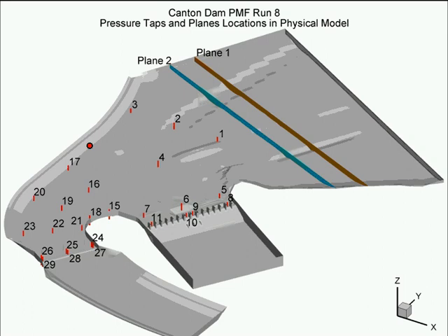What we used CFD for was to test a large number of different approach channel alignments as we come through this area here to find one that, one, gives us the water surface elevations that we desire, and two, tries to minimize excavation requirements. The two spillways are so close together that they are hydraulically linked, if you will, so a change to the fuse gate spillway will actually change the discharge coefficients of the existing spillway.